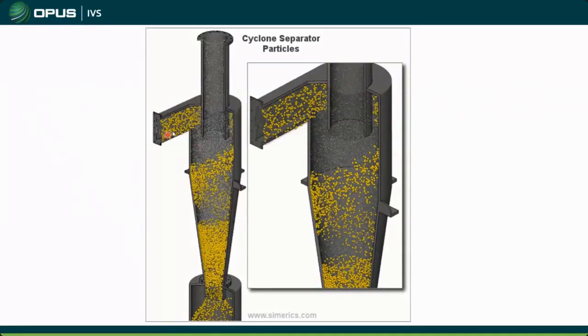As the air and oil come into this system, we have a swirling action. That swirling action pushes the oil out of suspension in the blow-by gases. Our blow-by gases continue to come up this tube, and our oil, steadily concentrating on the walls of the cyclone here, will drip down and end up back in our oil pan, back in the crank somewhere.